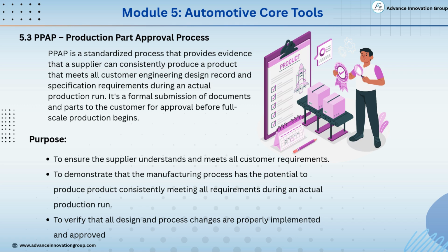Main purposes of PPAP are to confirm the supplier understands and meets all customer requirements, to show the process can repeatedly produce quality parts, and to validate that all design or process changes are correctly applied and approved. PPAP builds customer trust before mass production begins.